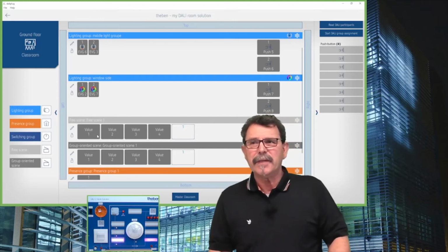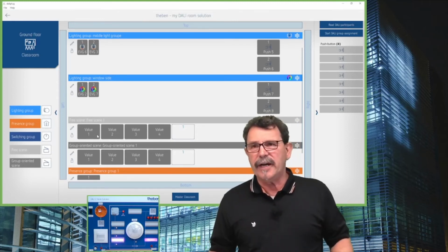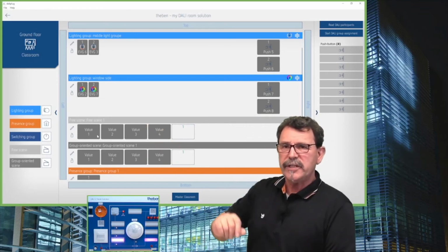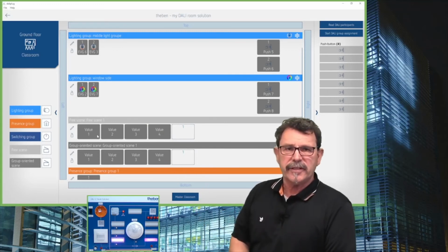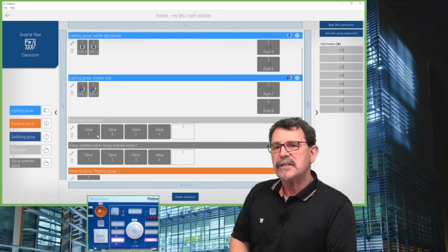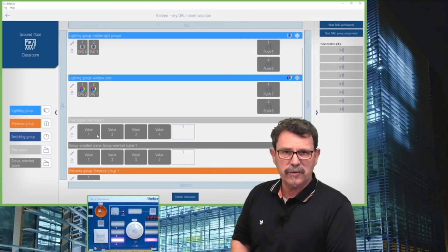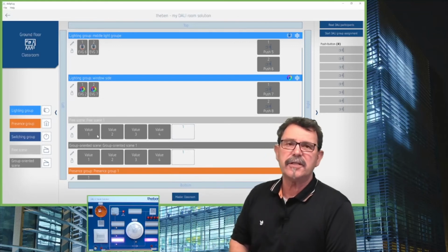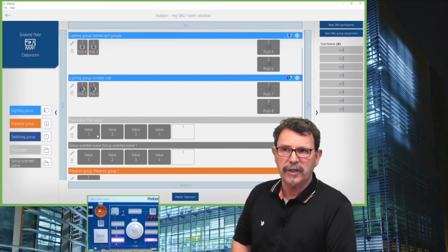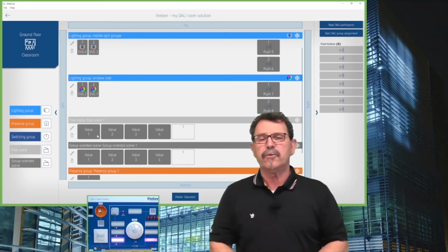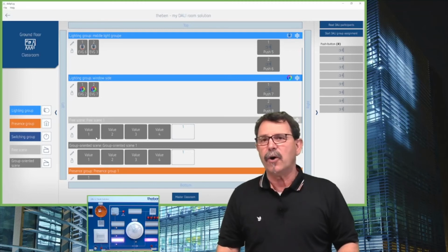In the next step, we want to define some scenes. Basically, we have to distinguish between so-called free scenes and group-orientated scenes. What is the difference? Group-orientated scenes means you just set one value and put it on some switch gears, and all these switch gears will work according to this value. So call up, for instance, the same color or the same brightness or whatever. In a free scene, you can allocate reasonable values to different lights. So we will do this now accordingly.